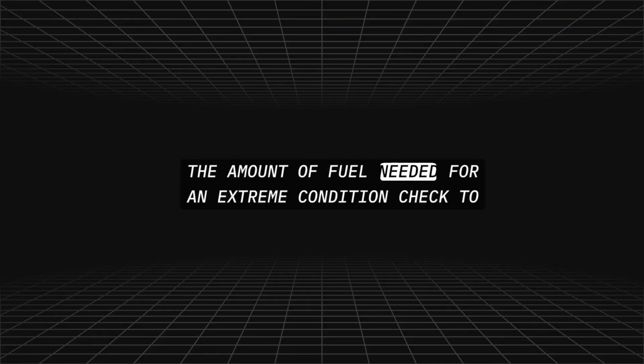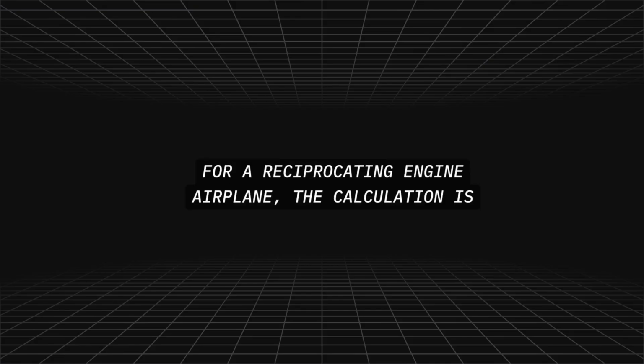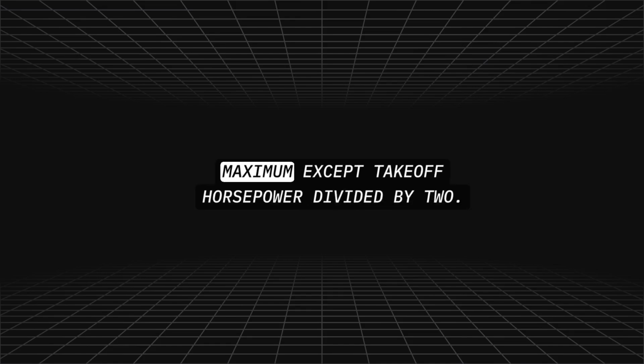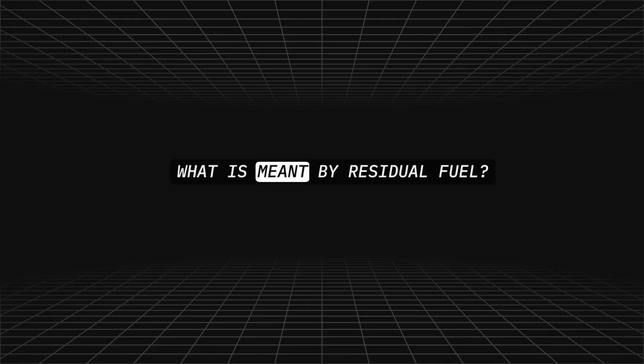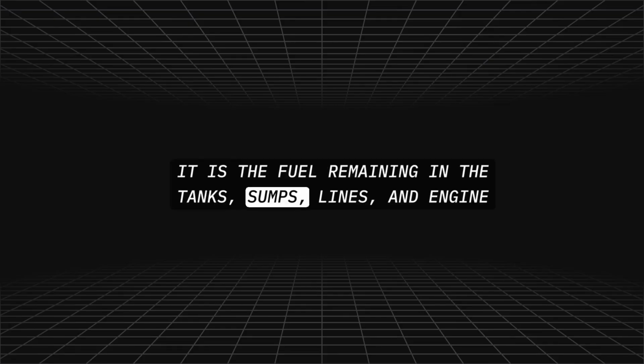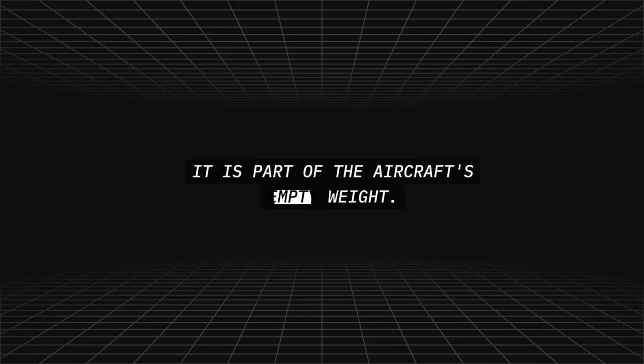The amount of fuel needed for an extreme condition check to see if the center of gravity will be out of limits in that situation. For a reciprocating engine airplane, the calculation is maximum accepted takeoff horsepower divided by 2. What is meant by residual fuel? It is the fuel remaining in the tanks, sumps, lines, and engine after draining. It is part of the aircraft's empty weight.